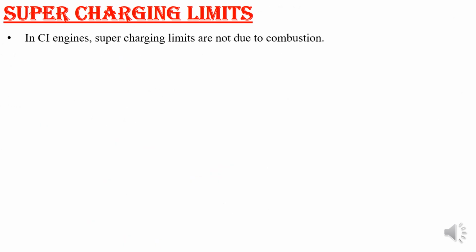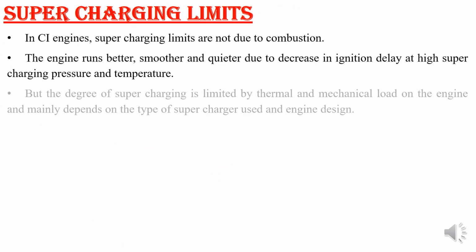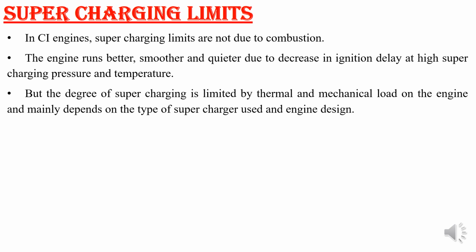Next, the CI engine. In the CI engine, as already told, because of the thermal loads we have to take care, because in a CI engine only air is going inside the cylinder and fuel is injected at the end, so delaying the ignition period will lead to a lesser tendency of knocking in the CI engine.